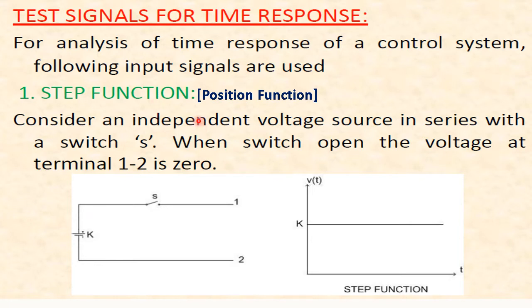Now, many signals are available which are functions of time and can be used as a reference input for various control systems. These signals are step, ramp, sawtooth, square wave, triangle, etc. But while analyzing the system, it is highly impossible to consider each one of them as an input and study the response. Hence, from the analysis point of view, those signals which are most commonly used as a reference signal are known as standard test signals.